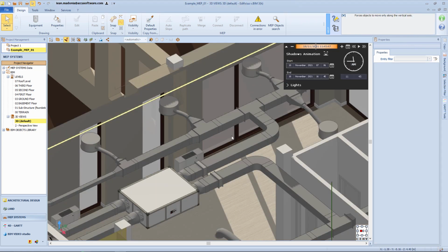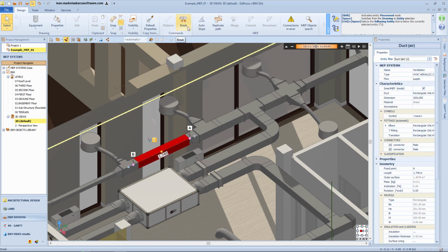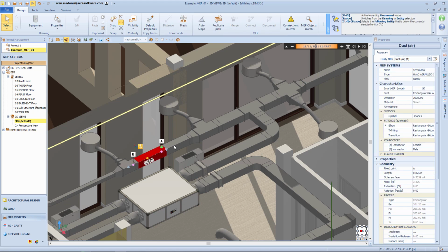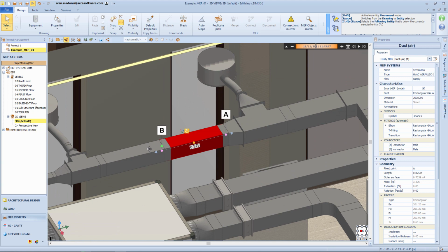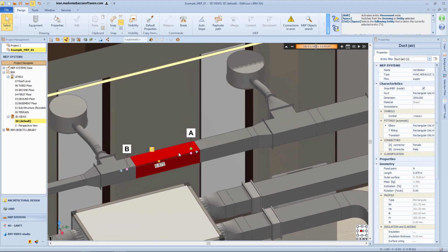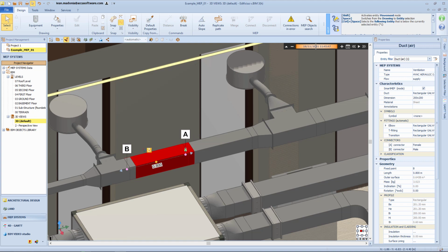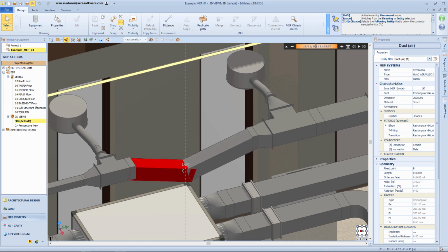If, on the other hand, you select any entity of type pipe or duct already modeled on the drawing, the break option is enabled in the Commands section of the upper toolbar. When this command is activated, the selected connection entity is precisely split into two non-separate segments. The pipe will be divided in the center, where a joint will be automatically inserted to keep the two equal segments thus generated together. However, you will then be able to use the gray arrow to move the position of the joint on the pipe or to type a value from the keyboard and thus modify the length of the two segments obtained. Using the other graphical tools available at the joint, you can reshape the pipe profile.